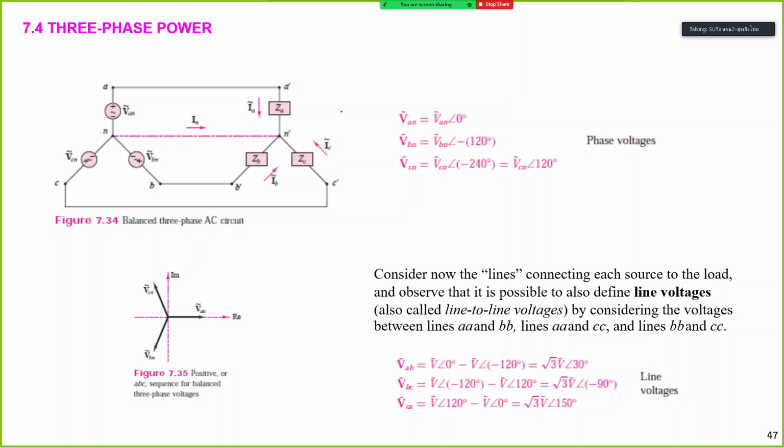In the three-phase electrical system, we have phases, normally notated as phase A, B, and C. Each phase is shifted from the others by 120 degrees. For example, if phase A is used as the reference, phase B lags phase A by minus 120 degrees, and another minus 120 degrees for phase C, like this.